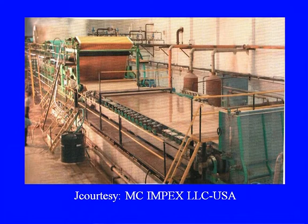Various rolls are there on which the wire part is supported, and after this the suction couch is there where we apply vacuum for removal of the remaining water. Here you see the drainage property of the pulp is very important. That is why beating and refining are very important parts, and the smoothness of the paper you are making on the wire part.